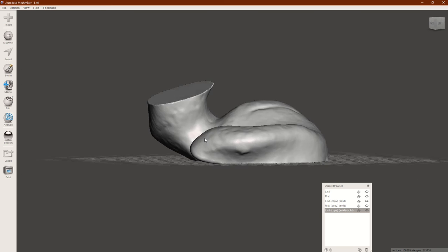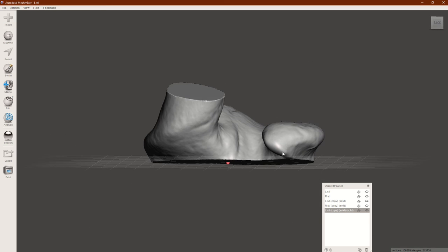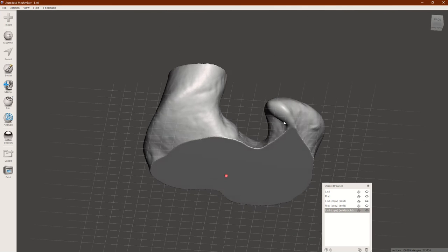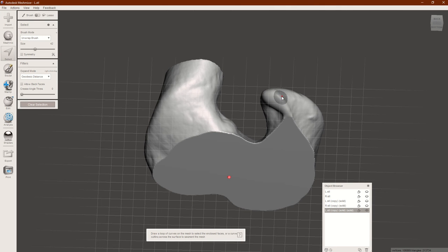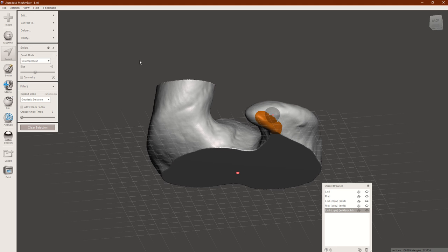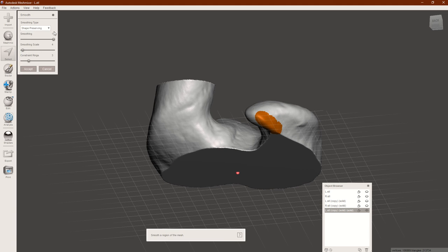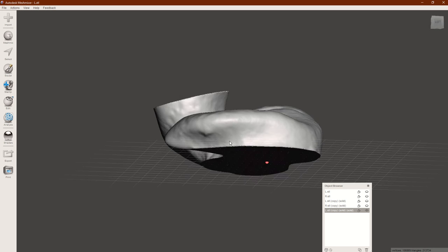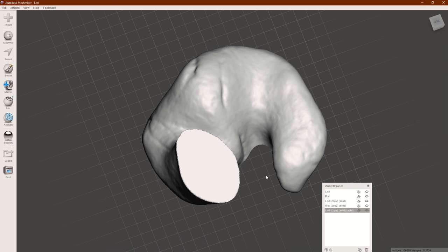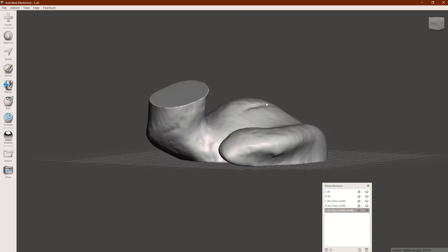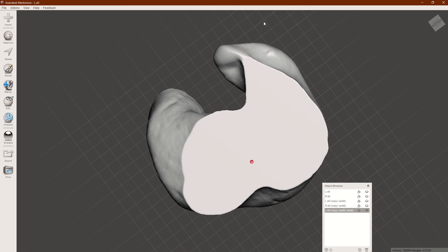Looking at that, you can now see we've smoothed it out. Now there's a bit of a knife edge here. It doesn't look like it, it looks pretty smooth, but that's actually going to hurt because it's not really smooth like we would like. So I'm going to select that knife edge-ish part. Deform, smooth, max smoothness, accept, clear selection. Okay, that's pretty good for now. You might even take a plane cutter and trim some back here and redo that process if you don't like the way it fits when it's done. But to me, this looks like it'll be great.